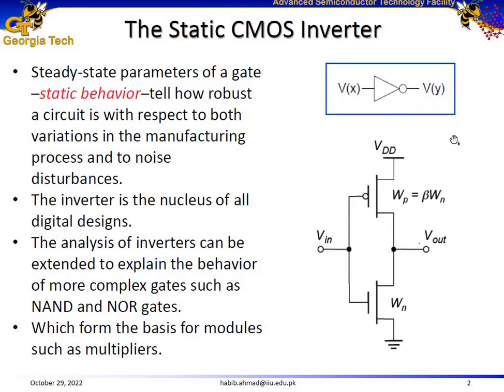Here is the symbol for the CMOS inverter, and as we have already discussed so many times, the CMOS inverter, complementary metal oxide semiconductor, does have an NMOS and a PMOS. The PMOS is connected to VDD, and the NMOS is connected to ground. Right. I'm going to need responses from you as well. And the input is connected to the gates of the PMOS and to the gate of the NMOS. And then the output is connected...